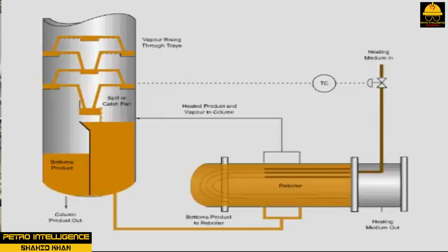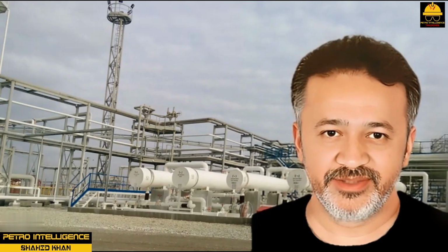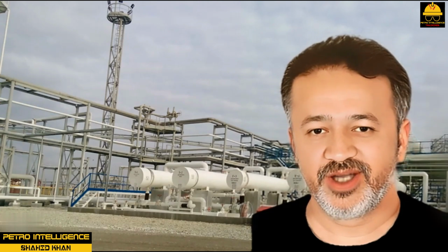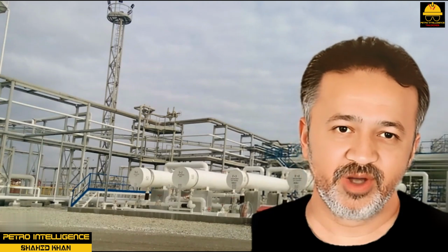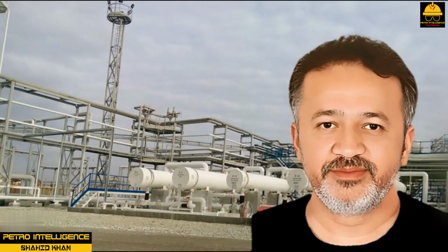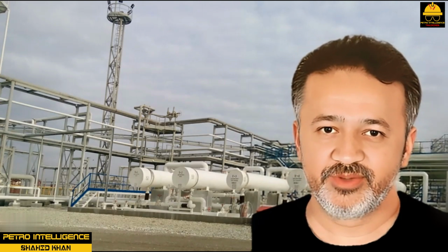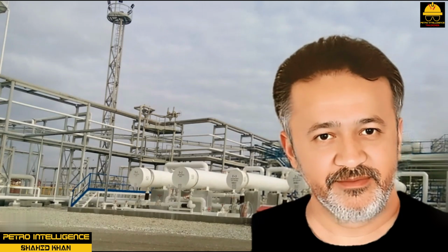The lower tube inlet of the exchanger usually takes suction at a point low enough on the column to provide a liquid level to the exchanger. A pump is not connected to the column and exchanger unless a forced circulation system is required. This system uses buoyancy forces to flash off and pull in liquid. Newton's third law of motion, which states that for every action there is an equal and opposite reaction, is a basic operating principle of thermosiphon reboilers. As liquids and vapor circulate back to the column, the inlet line provides fresh liquid to support the circulation.